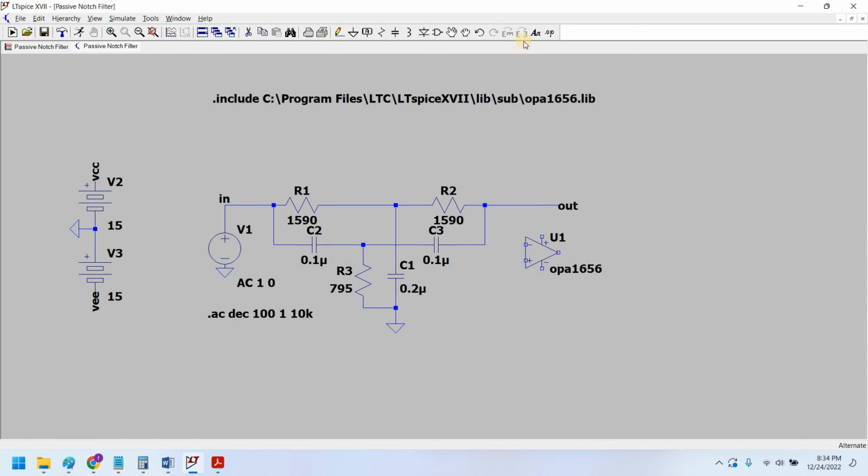Okay, so now we would simply delete this wire here, and we would simply connect this input at positive, and we connect the VCC to positive VCC and negative VEE to negative. I have configured this non-inverting buffer configuration of the op-amp, and this would enable us to have our attenuation controlled at minus 20 dB level.